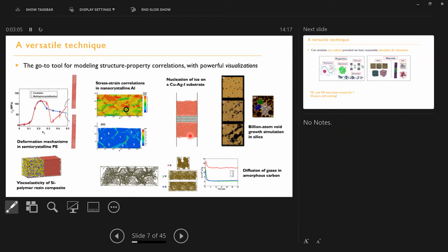This structure we created by using a random distribution of carbon atoms in a simulation box, and then we used a reactive potential that can give you this bond formation. When you quench the gas-like carbon atoms to room temperature, they will self-assemble to form such a disordered carbon, or amorphous carbon. So there is a method for doing it. I can share the reference later on if you're interested.